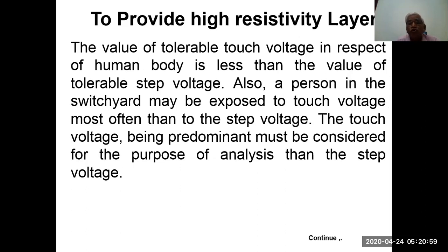Also, a person in the switchyard may be exposed to touch voltage more often than step voltage. The touch voltage being predominant must be considered for the purpose of analysis rather than the step voltage. Like in a substation, the junior engineer goes for taking the meter readings. At that time, he may be touching the distribution board or the transformer, that is the touch voltage with respect to the ground.